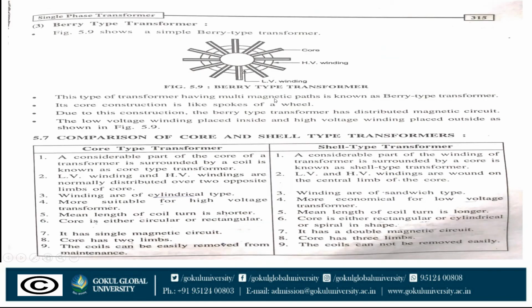And third one is Berry type transformer. This type of transformer having a multi-magnetic path is known as the Berry type transformer. Due to this construction, the Berry type transformer has a distributed magnetic circuit. The low voltage winding is placed inside and the high voltage winding is placed outside as shown in the figure. See here, low voltage winding is inside and the high voltage winding is kept outside.